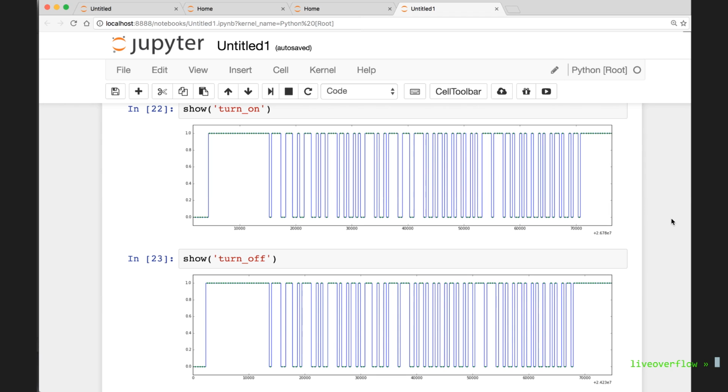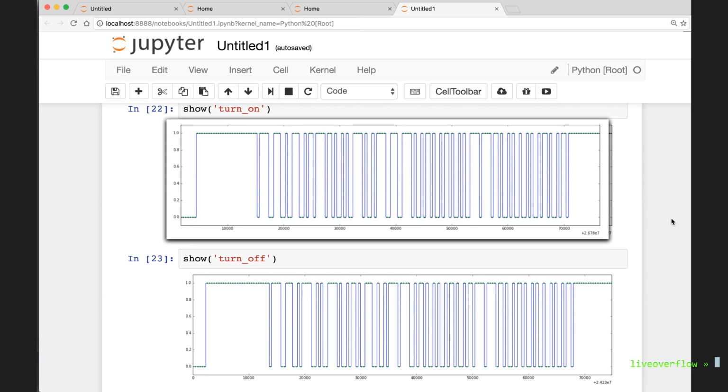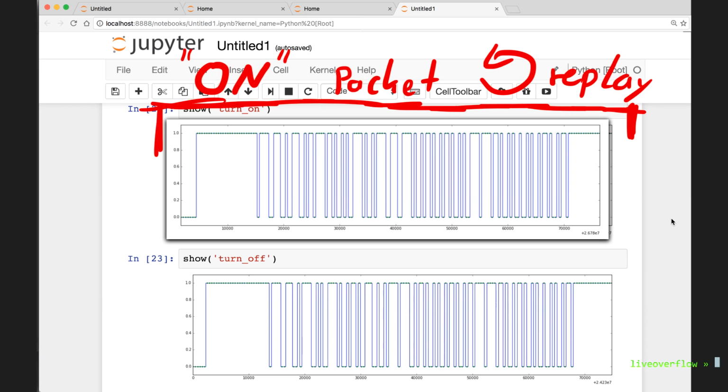So one attack you can do without knowing the protocol is to compare multiple packets of the same command, like multiple turning on packets, and then you could see that this is always the same. So there's no crypto or timestamp or whatever involved. So a replay attack is easily possible. Without knowing what the bits mean, we can just resend the pattern to perform this action.